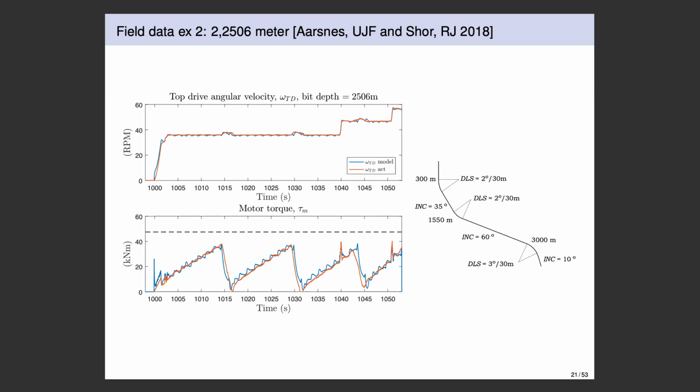because on bottom you have only the ROP as an axial velocity, but in the off bottom condition, if you are reaming up or reaming down, you have an axial velocity which will combine with the torsional velocity, and your friction force, in a very, very simple approximation, will be constant at any contact points, but will split between the axial velocity and the rotational velocity components. Right. So what I would expect in that situation is that we will see changes in the kinematic and static friction estimates, incorrectly attributing the effect of velocity to these coefficients.